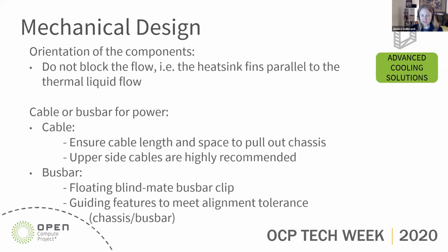For cables and bus bars being used for power. For cables, you've got to ensure that the cable length and the space available are enough to be able to pull out the chassis if you need to get it out and service it. And upper side cables are highly recommended. So this again comes back to, if you're dealing with a tank installation, there's one side of the chassis that will be accessible, the top side, and that's where you would like to have all of your cables going in and out of.